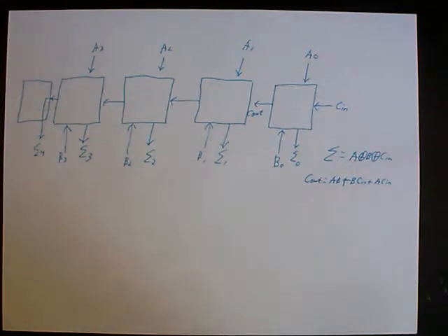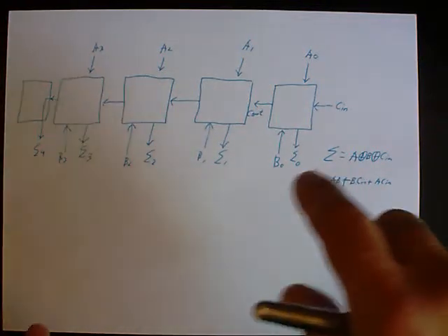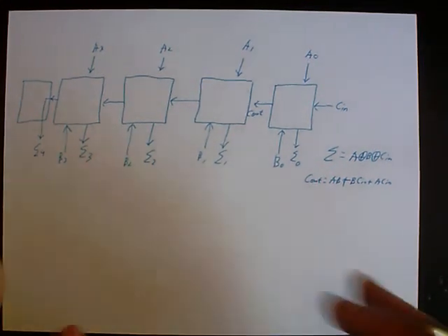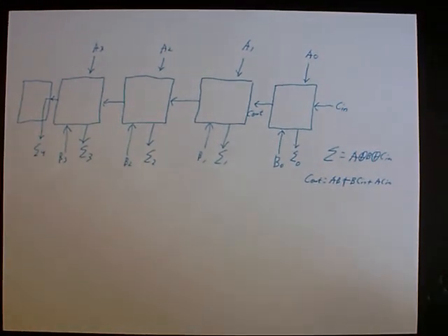The nice thing is, if you wanted to make an adder of 128-bit numbers, you could repeat this pattern just out to 128 cells, and you have a very large ripple carry adder. Now, the propagation delay of a ripple carry is not something you want necessarily when you're adding 128 cells. But the idea is, if you have an atomic unit that you can repeat in order to scale up your design, this is an architecture that supports that very naturally.